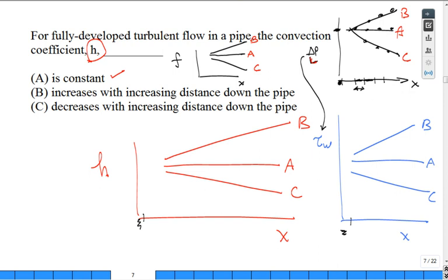Same pipe. Good question. Yeah, don't change the wall roughness. I didn't mention don't change the diameter either, did I? I should have said things like that. Ignore temperature-dependent fluid properties: constant fluid properties, constant diameter, constant wall roughness. All right, I'm going to stop.